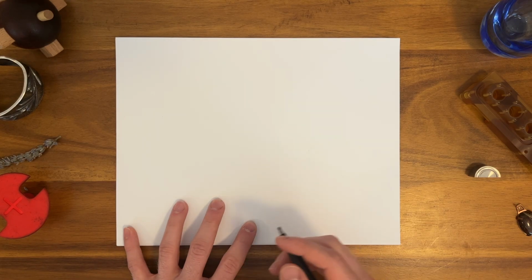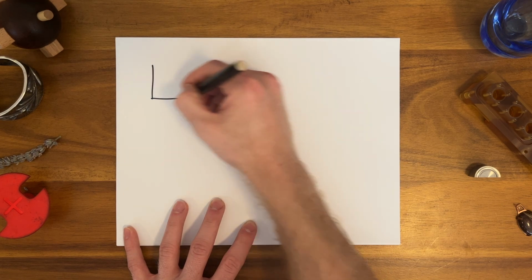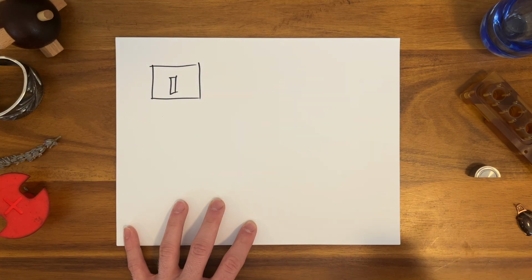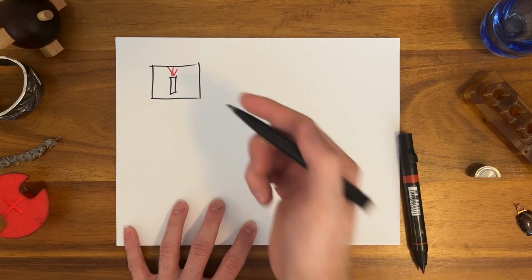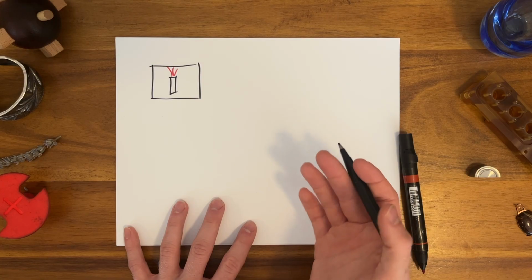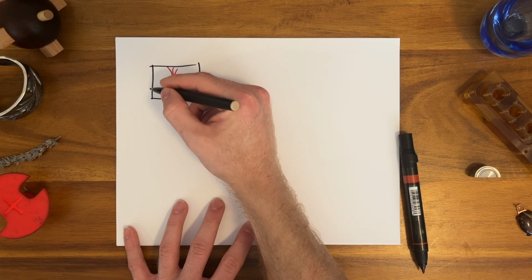The first issue was battery thermal runaway. Let's say you have a battery, it has an enclosure, and the battery inside has a bad day, there's some gas and flame, but you want to make your enclosure really light. Let's say it's thin aluminum. Is it going to burn through if it's exposed to a short duration at high temperature? Let's say it's a few seconds at 1000 Celsius going over this sheet.